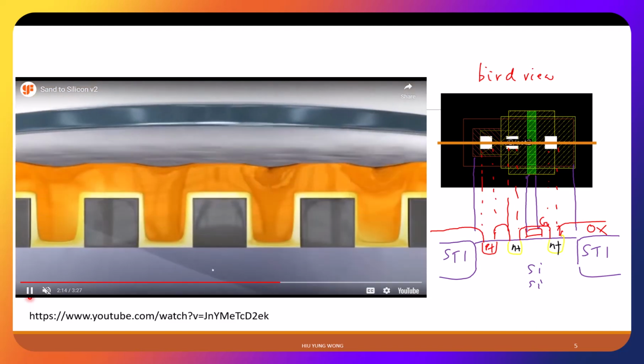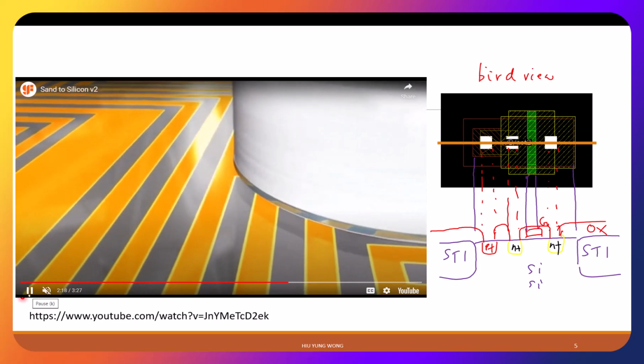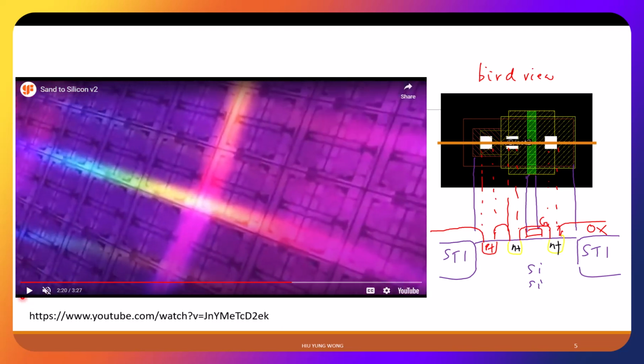It's called chemical mechanical polishing. This chemical mechanical polishing, called CMP, helps you polish all those uneven parts. Then your wafer becomes very flat. Then you can continue on the next layer. And that is a very important invention because in the past we used aluminum as the contact. In the late 1990s, almost 2000, right? IBM demonstrated they can use the so-called dual damascene process to use copper.